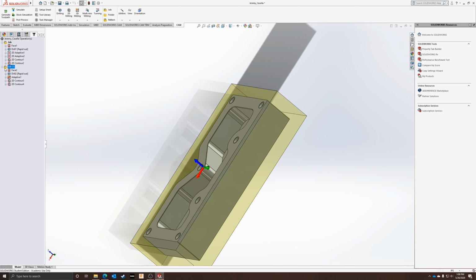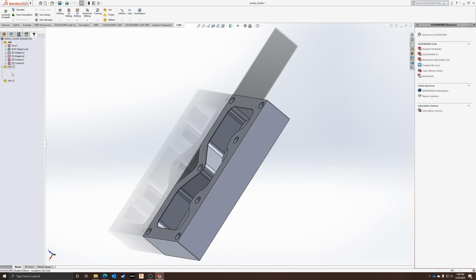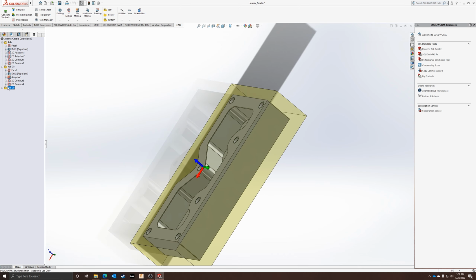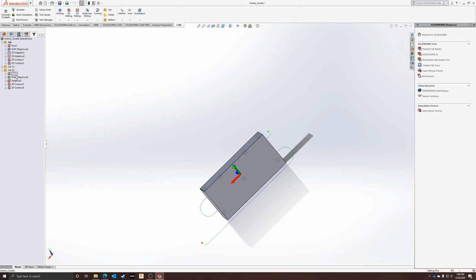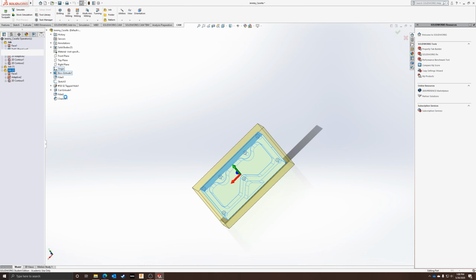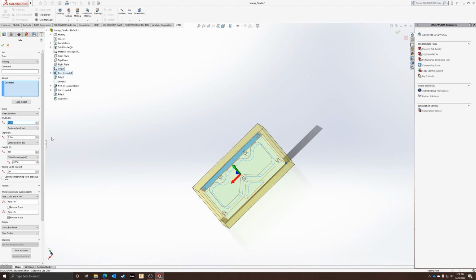So I'm just going to copy this job that I like. Control-C, Control-V, and then look inside of it and see that I got a facing operation, which I need for the backside. I've got a drilling operation. Don't need that. I have an adaptive, and I just need one of the contours, right? We just got to change some things. I got to pretend that I'm flipping it over now and think about what's on the back side. The stock dimensions haven't changed. All that's changed is Z.